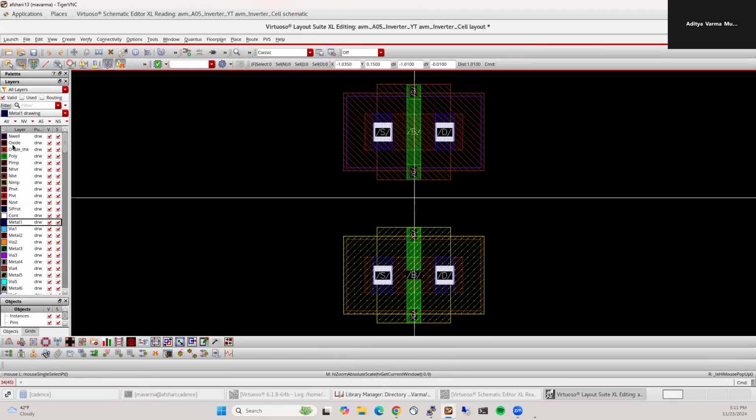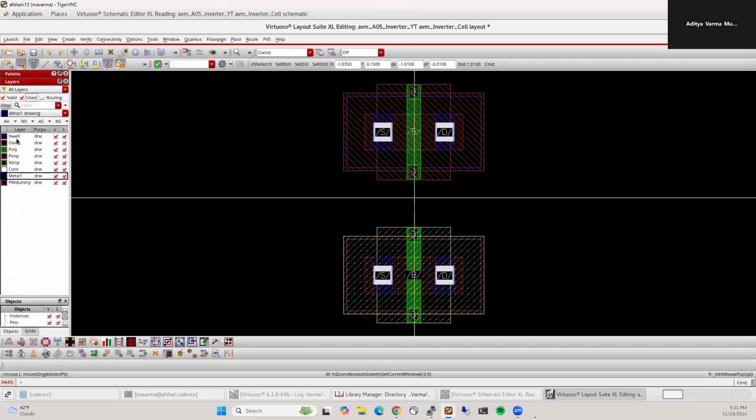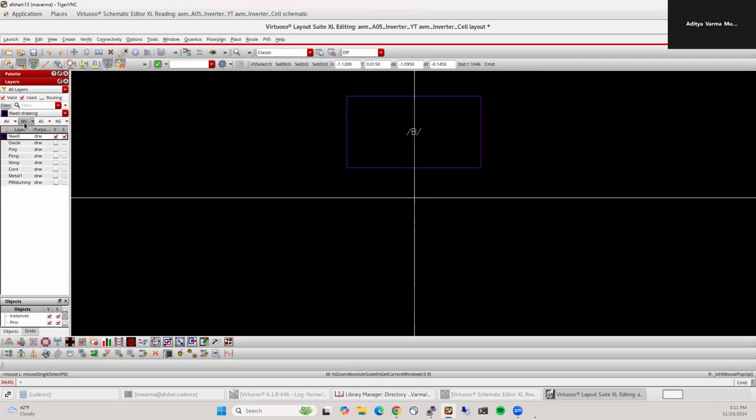So on the left, if you click on used layers, then we'll see the layers that I used in these two devices or in the layout right now. Let's say you have different layers. I would recommend you go and read about them separately and briefly talk about some of them here. So, you have an N well, so you can click on NW and you'll see only where the N well is. You only need an N well for a PMOS device, right?